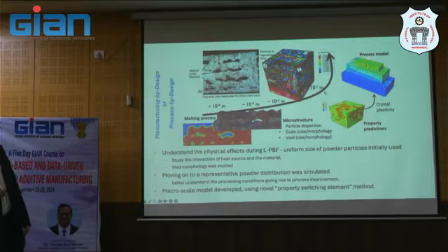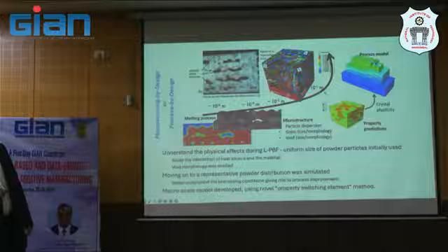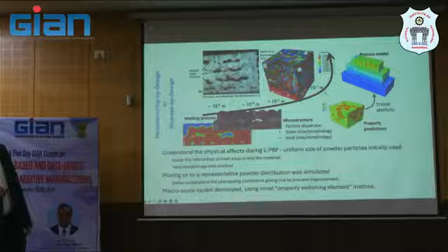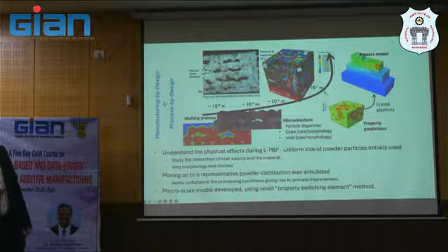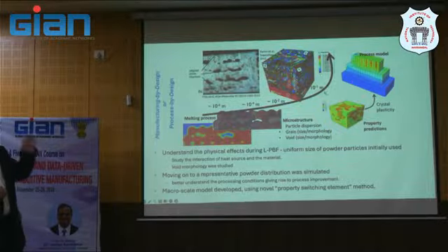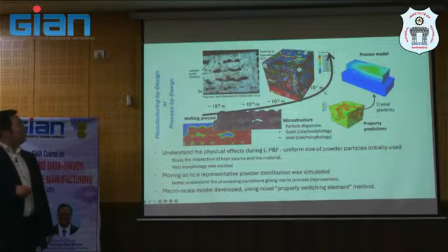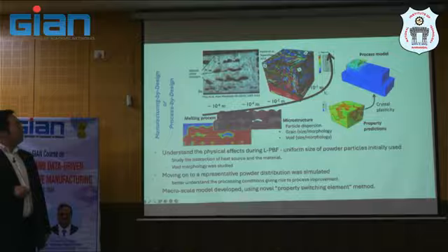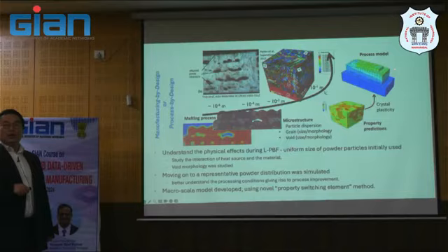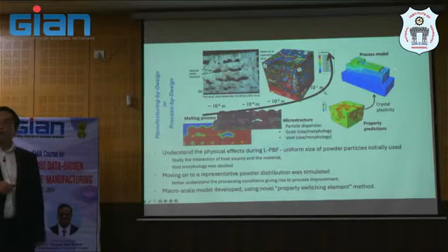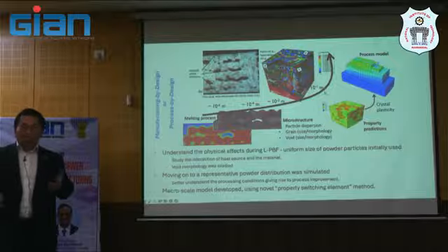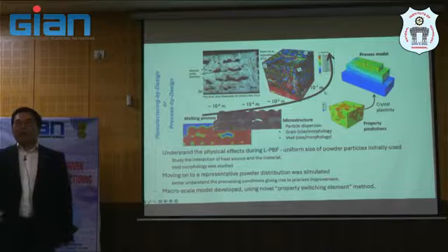And even when you deposit here, you will see that we need to implement some clever kind of, we call it a switching function, that does not assign a homogeneous property in the deposition voxel here. It has to be some distribution of property, what we call a property switching function. So we need to switch the property at each deposition differently in order to take into account all the lower length scale information. Still, work is going on. It's not robust. It's not done yet.